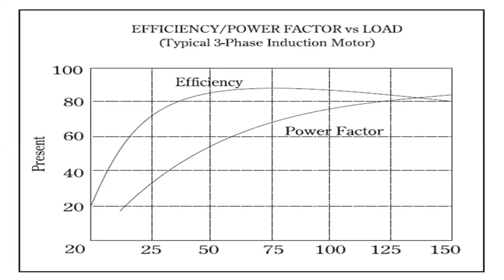Performance of an induction motor on partial load can be seen from the graph. It will be observed that the best performance of the motor is nearer to the rated output. The power factor is also improved as the load approaches the rated load. Hence, the performance of the motor depends very much on the load on the motor. Thus, loading a 10 HP motor with 9 HP load is far superior to loading a 15 HP motor with 9 HP load. That's exactly what we understand.